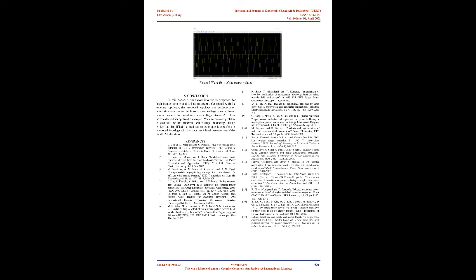In order to generate all voltage levels, even and odd, at the output, 4 different algorithms are proposed to determine the magnitude of DC voltage sources. 3 Proposed method. Pulse width modulation, PWM, is the simplest technique that can be implemented in multilevel inverters. A 9-level inverter employing 1 voltage source and 2 capacitors is proposed for power system.